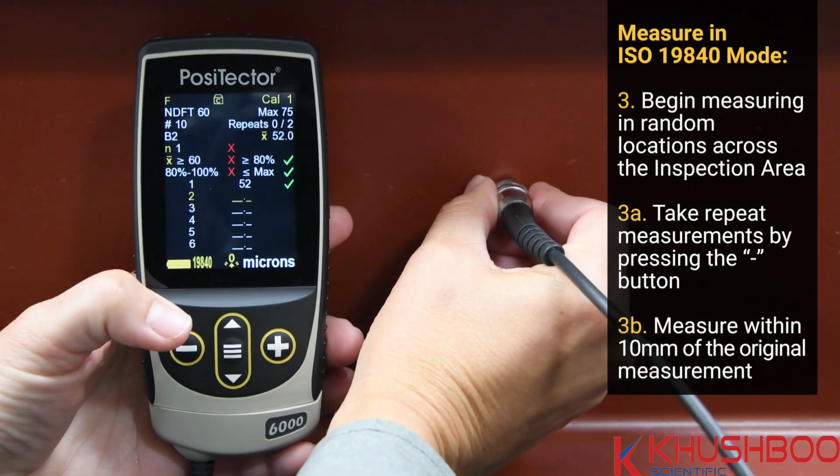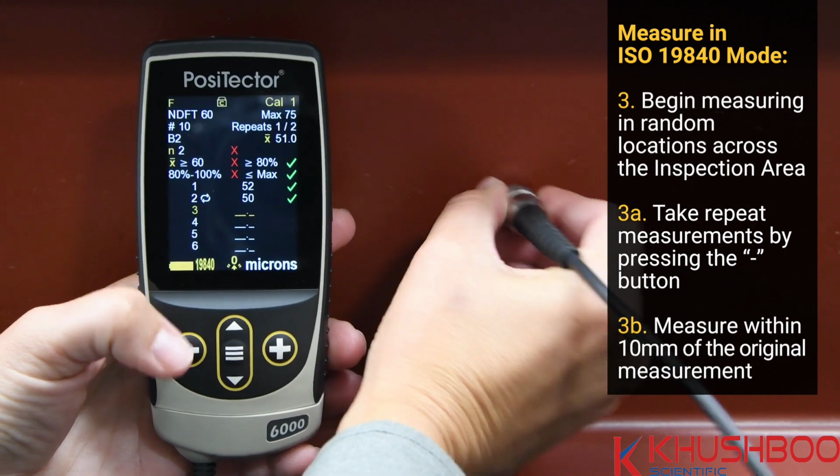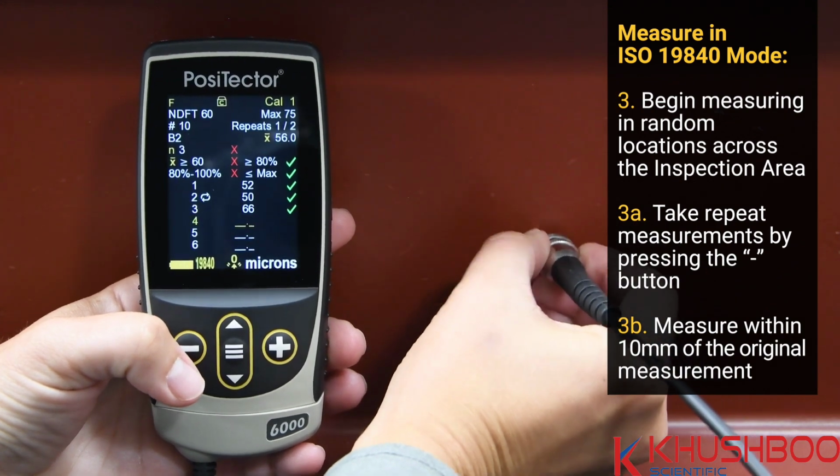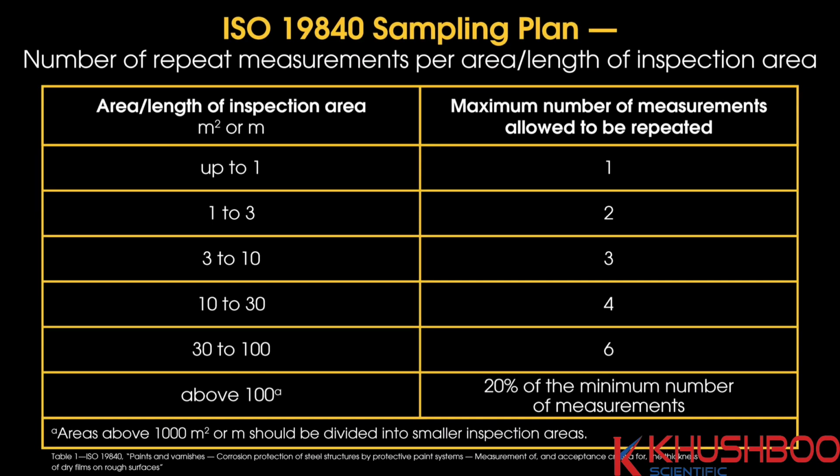Take a repeat measurement within 10 millimeters of the original measurement location. If the repeat measurement still does not meet the criteria, that measurement cannot be deleted and retaken. The maximum number of repeat measurements allowed in the batch is determined by the size of the inspection area.